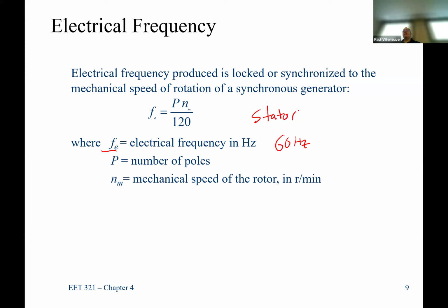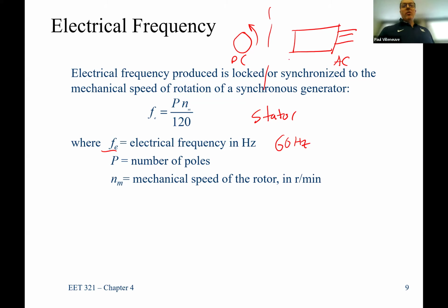So interestingly enough, with an AC machine, we have two separate circuits, right? We have a rotating circuit that's fed DC, and we have a stationary one with 3 phases, and this is AC. So we have two completely independent circuits from each other. If we want to analyze these with circuit analysis, we have to analyze the DC circuit separately from the AC circuit. Because what gets induced over here is a magnetic field, and that's what creates the windings. So we electrically analyze the circuit over here, and it's DC, which flows a current, but then we get some way of calculating what the magnetic field is going to be, and then that rotating magnetic field in the stator winding is going to drive a current.